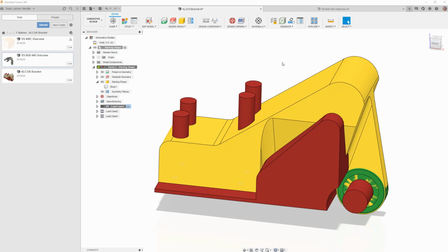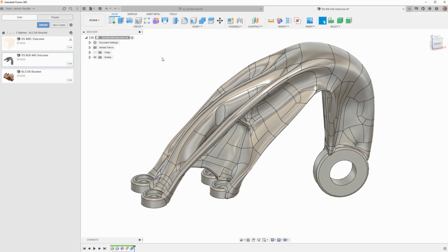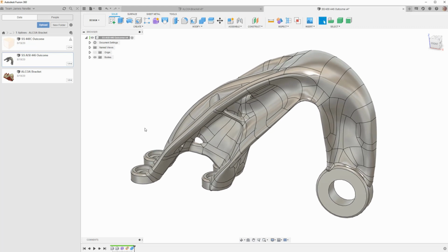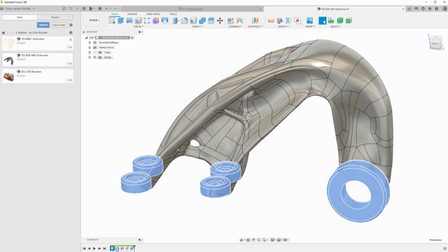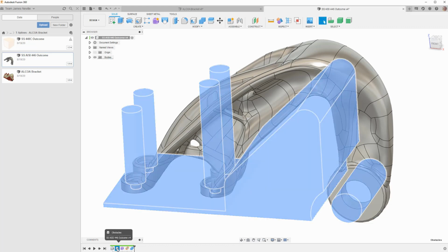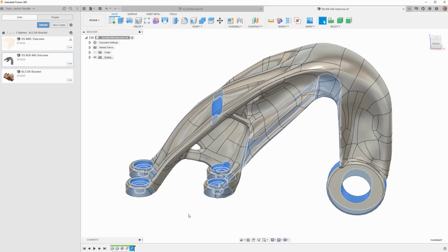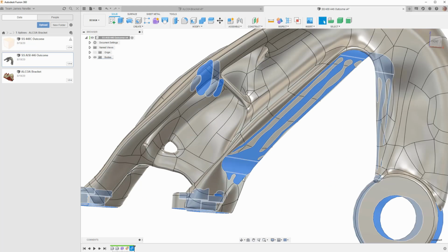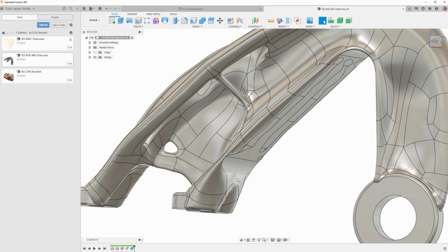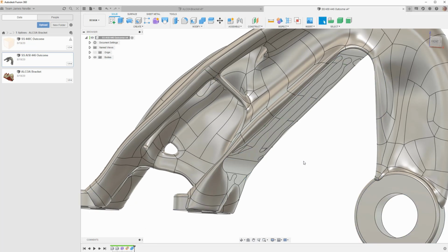So we've done our generative study, just advancing forward 30 or 40 minutes, and now we have an outcome. All right, so we're looking at this 446 stainless steel outcome, right? And much like we went through in the basics guide earlier, you've got your preserves, going through the timeline at the bottom, your obstacles, the form shape or the form body there, the boundary fill to connect it all together, and then ultimately the combined cut, which, like I've said before, I'm not a huge fan of. At least I'm not a huge fan of when it needs to be in play to get a good result. But this one does have a combined cut in it.